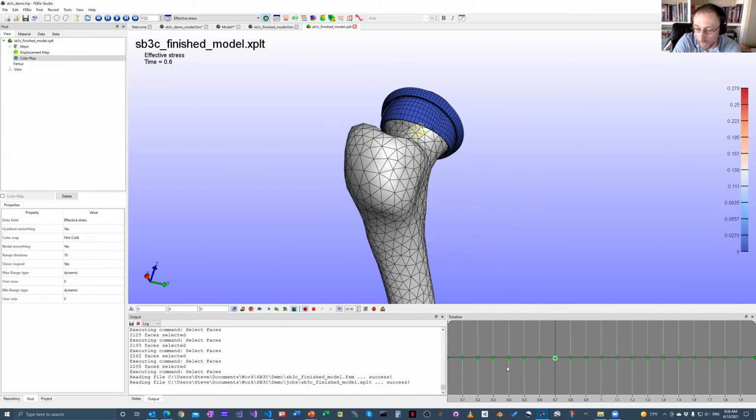For instance, if you want to get the slope of this first part here, you would select the source. In this case, let's do the green curve. Now that fits a curve to the entire domain, which is maybe not what we really want. So let's just select a few points here and then set selection. And now we can fit a slope to just the initial part to get an estimate of the slope of the initial part of the curve.